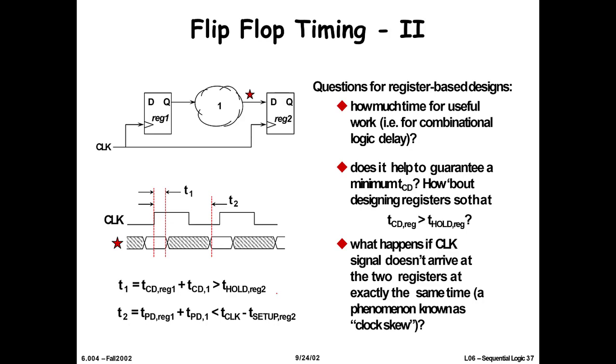So let's first consider what is the maximum frequency. This is our model, in which we have a register R1, we have a register R2, and between these 2 registers we have our combinational logic CL1. Now the flip-flops, this is flip-flop 1, flip-flop 2, work on the positive edges.